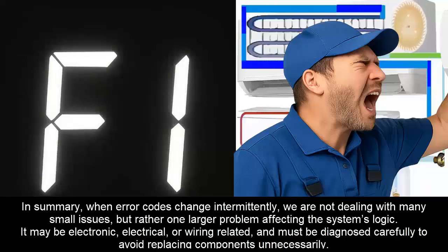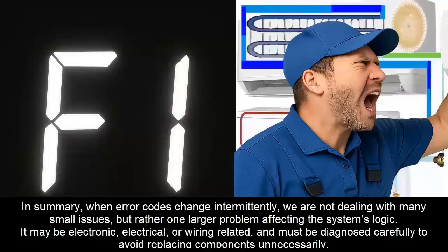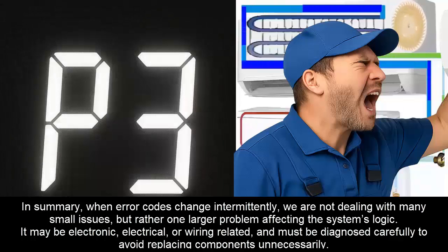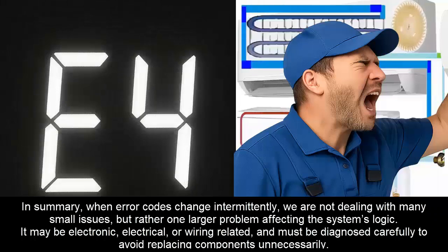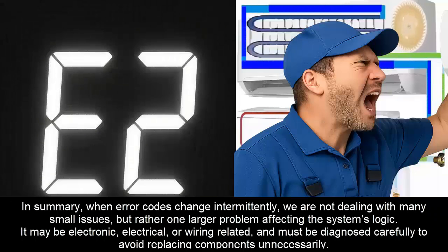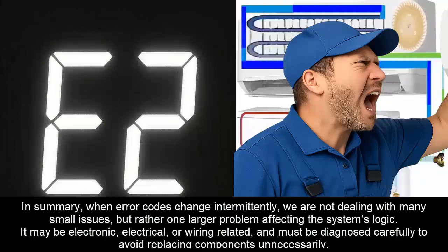In summary, when error codes change intermittently, we are not dealing with many small issues, but rather one larger problem affecting the system's logic. It may be electronic, electrical, or wiring related, and must be diagnosed carefully to avoid replacing components unnecessarily.